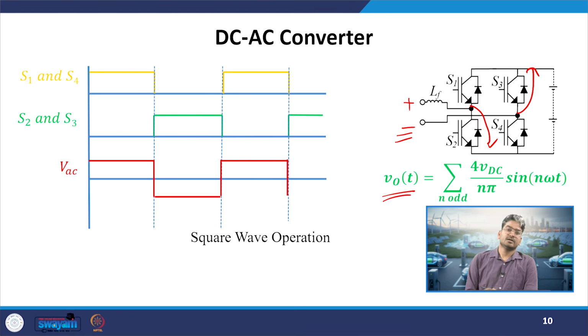Okay. So, what is the dominant harmonic? The dominant harmonic is the one closest to our requirement, or the next harmonic compared to our fundamental component. The fundamental component is our required frequency at the output. Other than that, whichever components are present are called harmonics. Out of all these harmonics, whichever has the least frequency is called the dominant harmonic. Why is it called a dominant harmonic? Because it will have the most effect on our load, because most of our loads are inductive in nature, since we generally have induction machines.